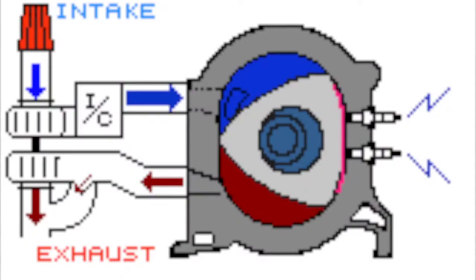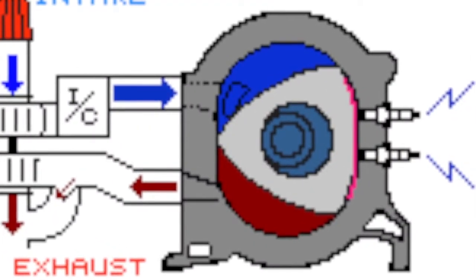Pretty interesting stuff. The function of the rotary engine is that the main principle of the engine is that it uses the pressure created when a combination of air and fuel is burned, which is of course how a lot of engines function. But the difference is that that pressure is contained in a chamber formed in a housing by a triangular rotor, which is what that engine uses instead of pistons, which makes that difference between the two. As the rotor moves around the chamber of the engine, each of the three volumes of gas alternately expand and contract, which creates that power that makes the rotary engine so awesome.